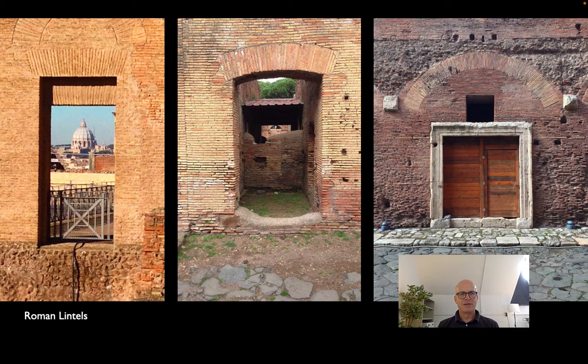You can see also that they've taken some of the load off of that lintel by putting an arch into the wall above it. These are called relieving arches. Invisible if you plaster the wall, but very important in taking the load of the wall above and spreading it around the window below, taking some of the load off of that flat arch. In the center, a segmental arch.